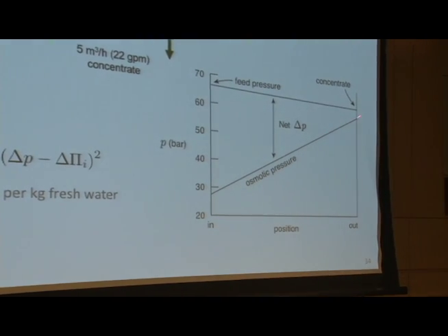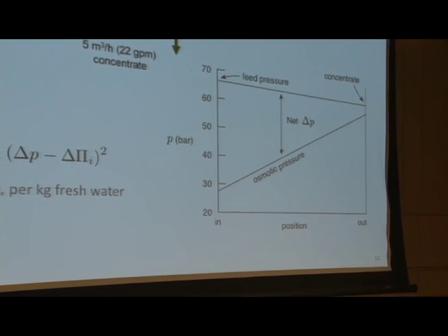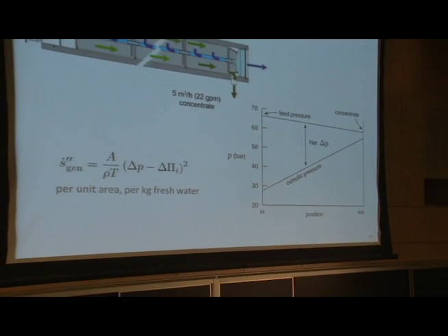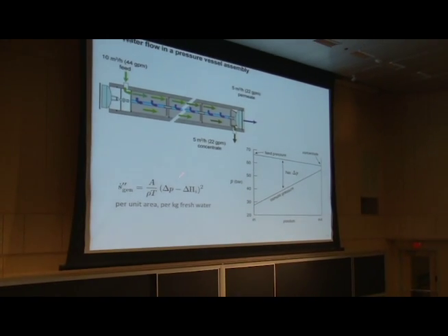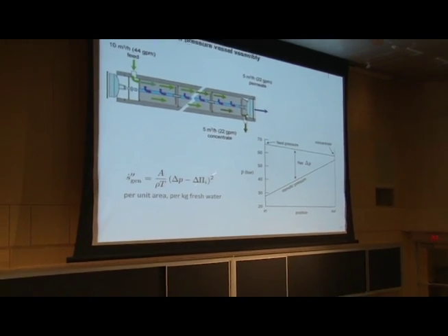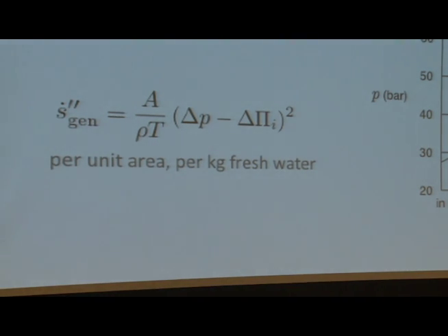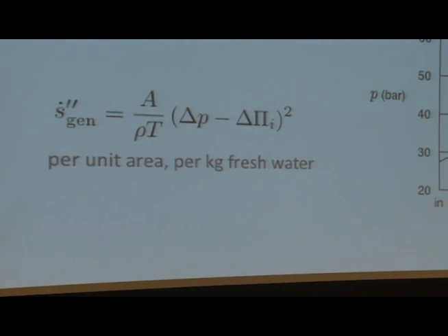And so you've got to set some higher pressure down here, and the only way to do that is to set a really high pressure at the inlet. So much of this device is greatly overpressured relative to what it ought to be if you just wanted the water to flow gently through. And it's a calculation, but you can find that the difference between these two squared is essentially the size of the entropy generation. So your engineers, what do you do about this?